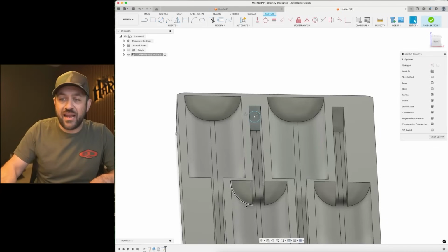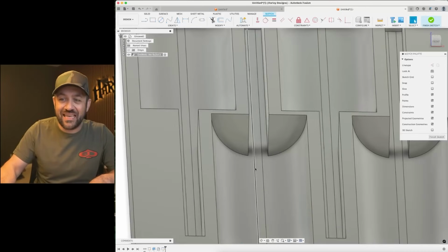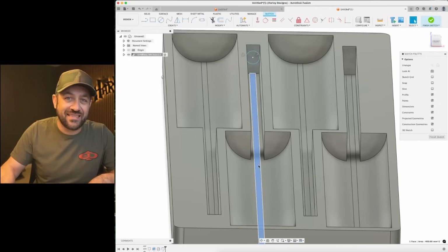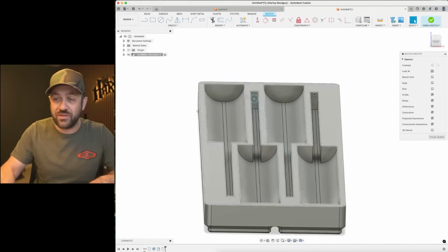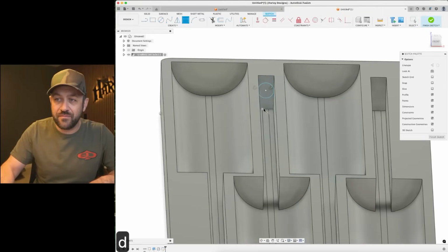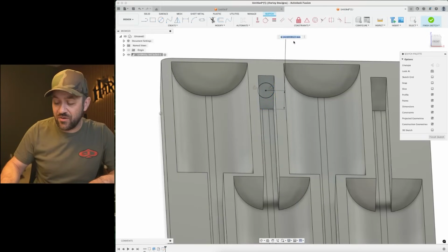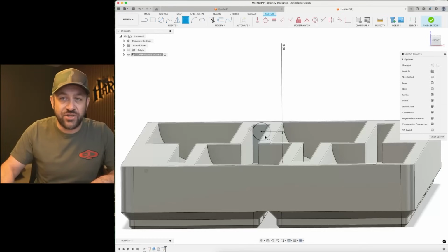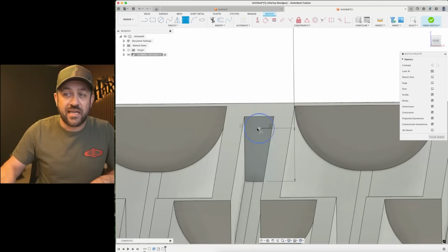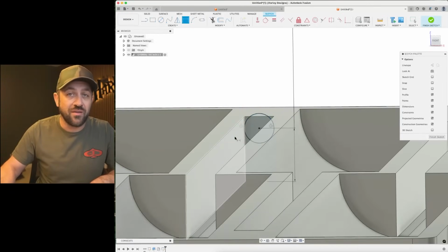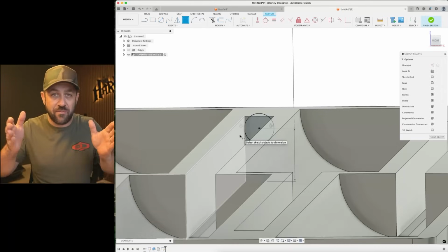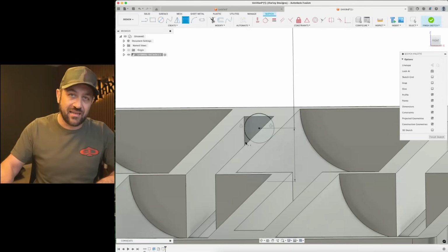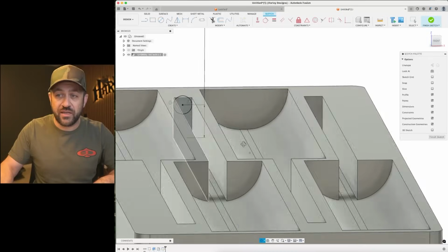And to center that, I want it to be basically the center distance off of this center flat, which, like I was saying, was 9 3/8 when I was doing the math. It's not super important. We could round if we wanted. Let's just go to 9. As you can see from that, the center point is slightly below that line of the pocket. So we'll have a comfortable amount of tool setting in there. It's not going to rattle its way out super easily.